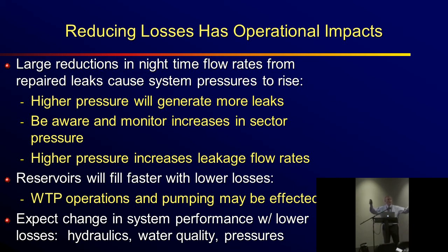You fix leaks, the pressures go up at night because the flows aren't there. Be aware and monitor increased pressures in your sector. High pressure increases flow rates. If you reduce some leakage, the pressure goes up, you leak more. Reservoirs will fill faster with lower losses. You have to change your standard operating practices for your reservoirs because you got more water availability. You can fill your reservoirs faster.